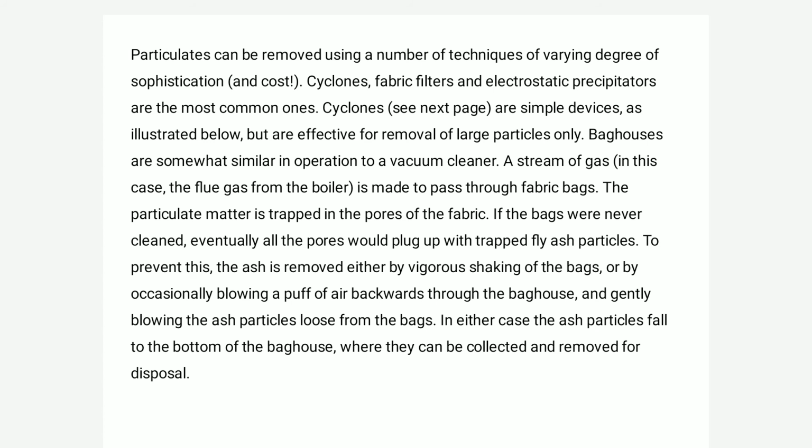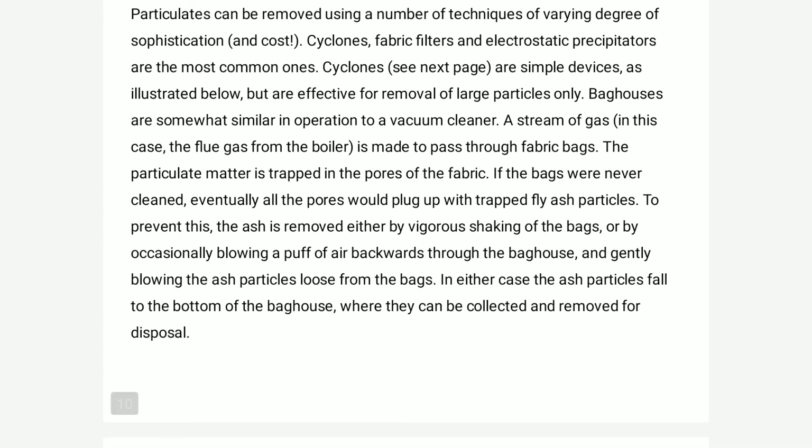The particulate matter is trapped in the pores of the fabric, and if the bags were never cleaned, eventually all the pores would plug up with the fly ash particles. To prevent this, the ash is removed either by vigorous shaking of the bags or by occasionally blowing a puff of air backwards through the baghouse, gently blowing the ash particles loose from the bags. In either case, the ash particles fall into the bottom of the baghouse, where they can be collected and removed for disposal.